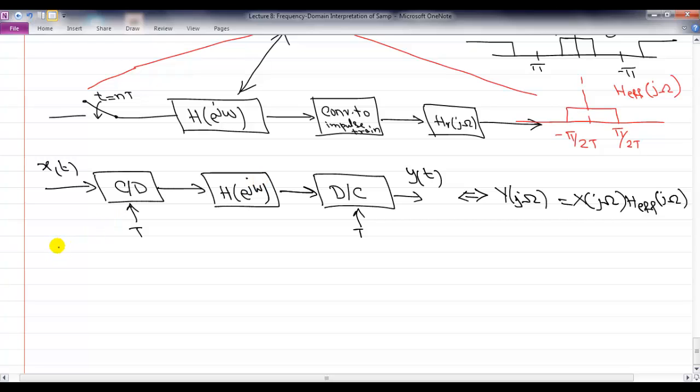You can also, since in digital systems you often can give the impulse response of your discrete system, ask, okay, is there a simpler way of going to the impulse response of this filter? So of course, H(e^jω) has an impulse response h[n], and you can first take your effective filter's frequency transform, go to the discrete filter, and then take an inverse DTFT. But is there a direct relationship between the impulse response of the continuous time filter and the impulse response of the discrete time filter?